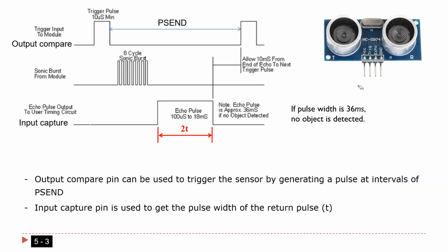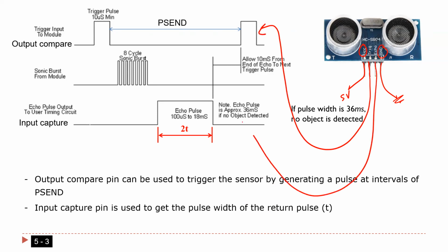So these sensors are used to measure distance. Okay, how are they going to be used? If you see here, guys, this pin is going to be VCC. So this one is connected to 5 volt. Okay, this one is the ground, as you see here. So this one is connected to the ground. Okay, and now we have 2 pins, as you see here. This pin is called trigger. So trigger is connected here, and we have echo. Echo is connected here. Okay. So it's not connected. It's going to read it. Okay. So this is the story.